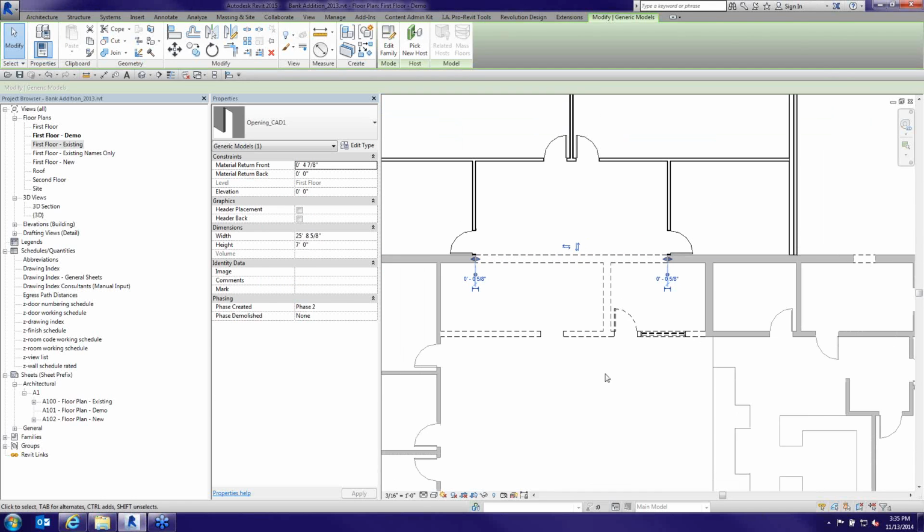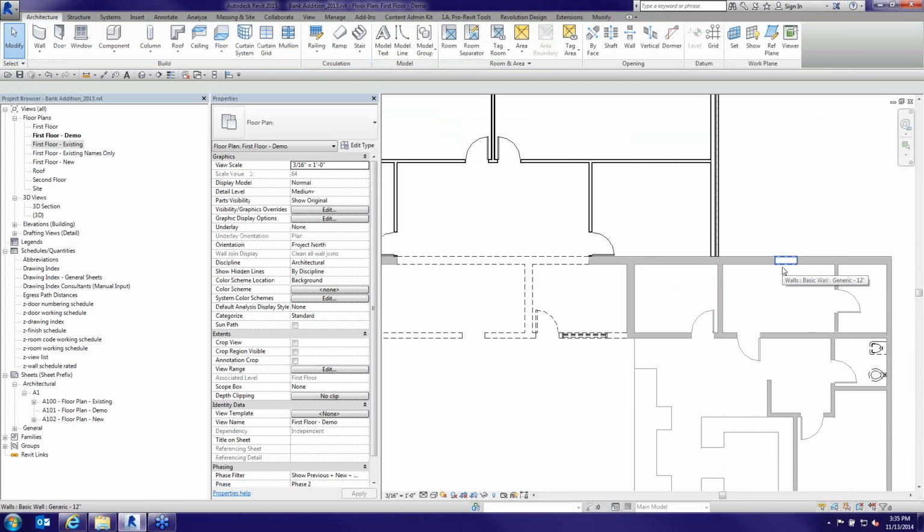And that would be the same thing for roofs, floors, etc. If I'm going to put a hole in a floor because I'm putting an elevator in this, or I'm moving the stair or whatever, I'm going to blow through that with a floor opening or a roof opening to do the exact same thing because I can phase those openings. If I go back and do a shaft or a vertical door or vertical opening, etc., opening by face, those don't have phases on them, so it's never going to allow me to say, hey, this looks like demo, etc.